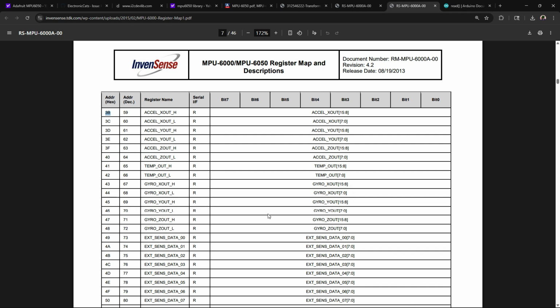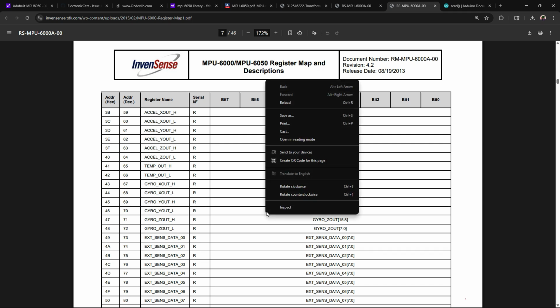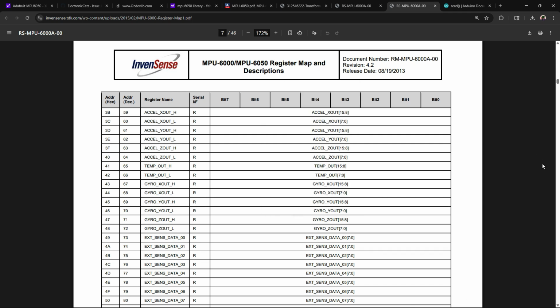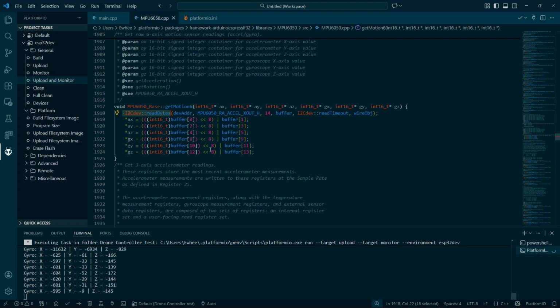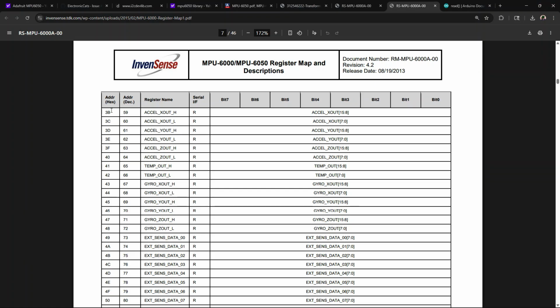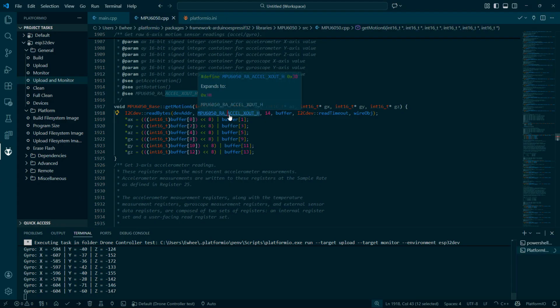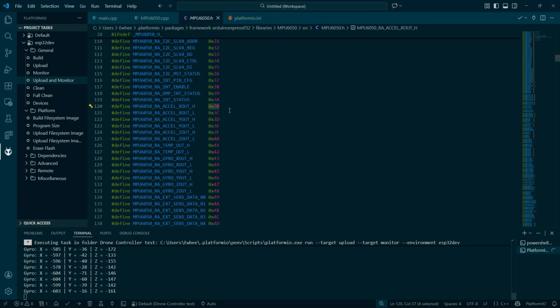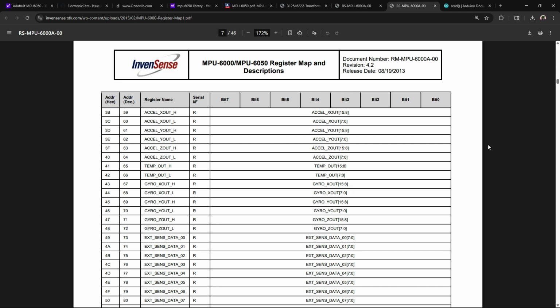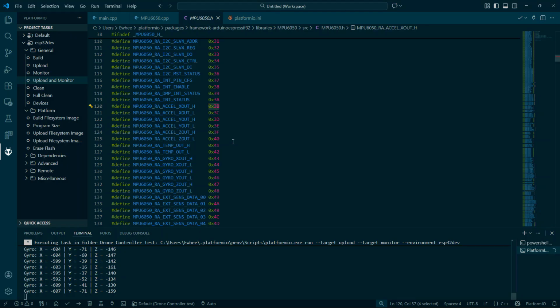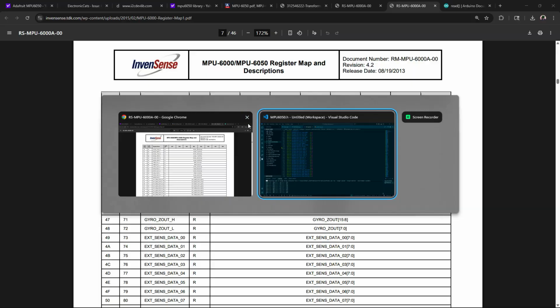So I have a genuine chip from Adafruit that I ordered off Mouser. It's pulling accelerometer X. Again, we'll go back here. Accelerometer X out high. Raw value, right? But that doesn't matter. And it's doing that at 3B. And again, if we go to here, you can see 3B. And this is somehow not accelerometer, and it's something else. What the heck is going on?